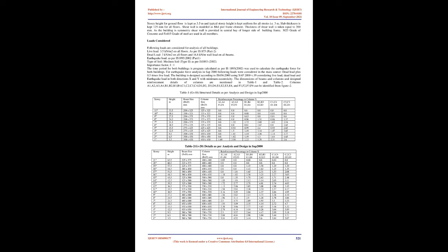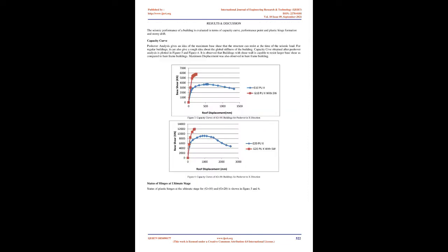The nonlinear properties in beams and columns have to be introduced for analysis, which can be done using predefined hinge properties in SAP 2000. The flexural default hinges, M3, were assigned to the beams at two ends. The interacting, P-M2-M3, frame hinge type, a coupled hinge property, was also assigned for all the columns at upper and lower ends. SAP 2000 takes auto hinge properties from the ASCE 41-13 tables.